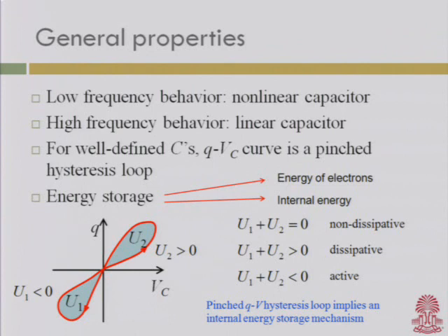The most interesting property of Mem-capacitors is the possibility of energy storage. Capacitors, of course, can be charged and can store electron charge, but for Mem-capacitors it's very important that they have some internal system, and this internal system can store energy even in the fully discharged state. So if we don't have any electron charge, we still can have some energy, previously taken from the electron system, stored in the Mem-capacitor.